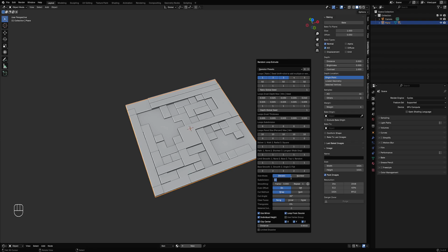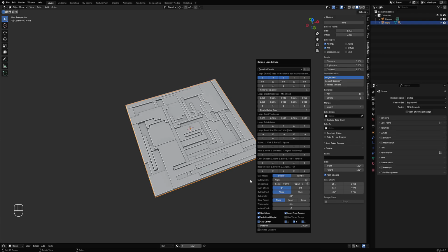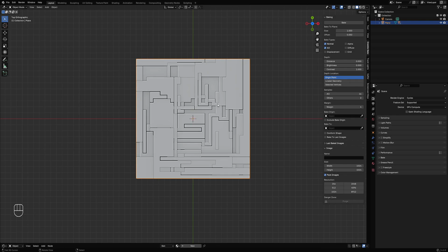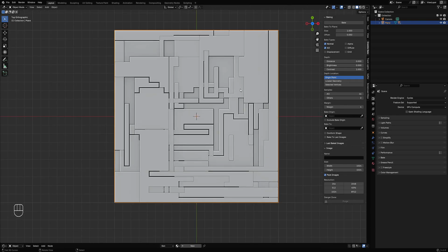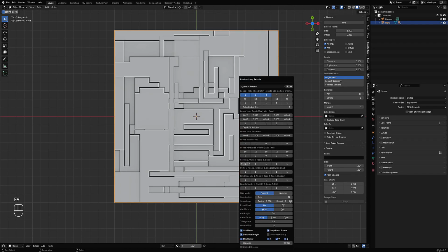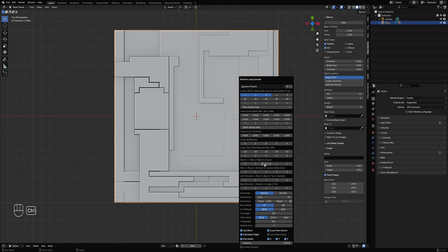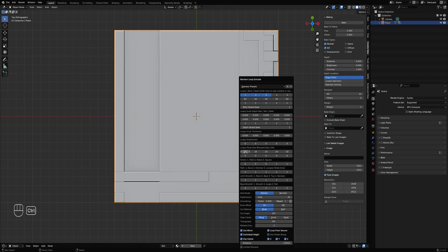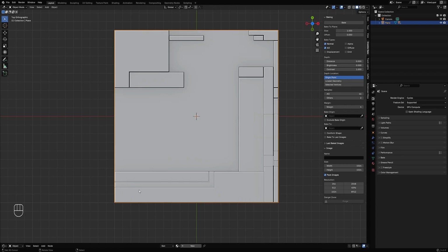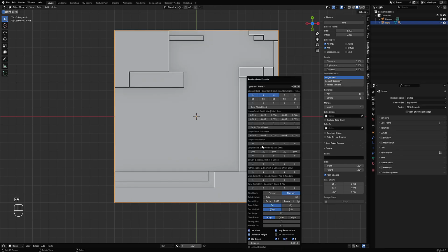So we might need to pump this up to level 32 to see some interesting patterns. Let's set the solver to square all of them, and panel size, this is in percent. You can change it to number like that.